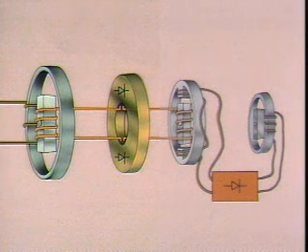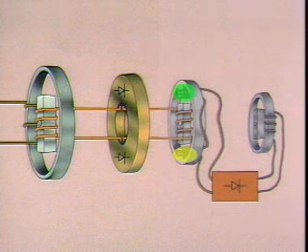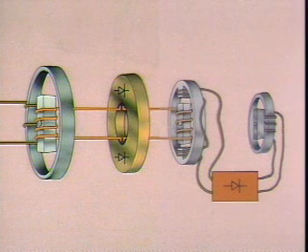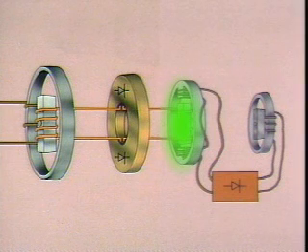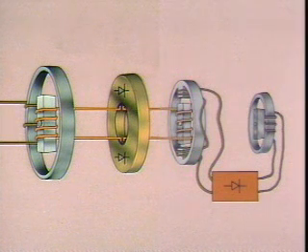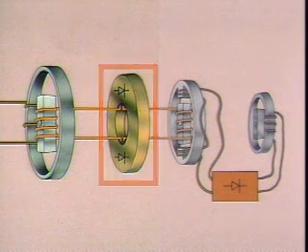The direct current flows through the stator windings of the exciter, creating a magnetic field in the stator windings. The magnetic field is used to induce alternating current, this time in the exciter's rotor. The alternating current is then rectified to direct current by the rotating bank of rectifiers.